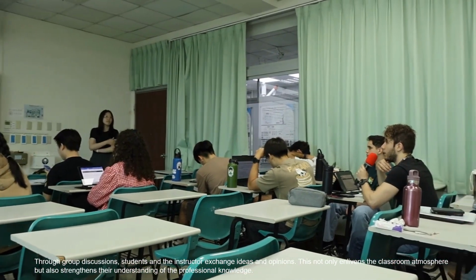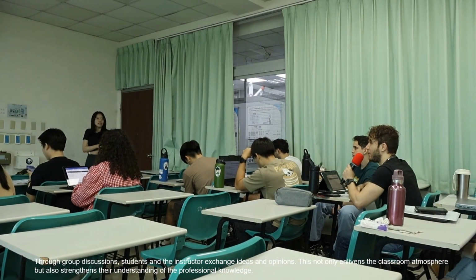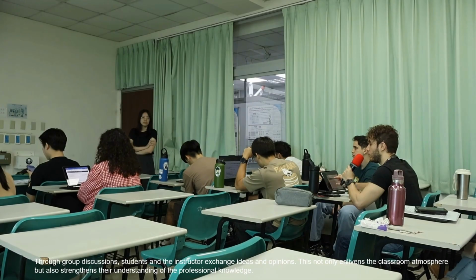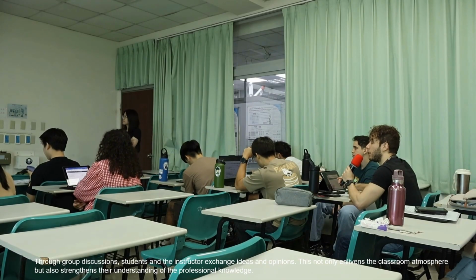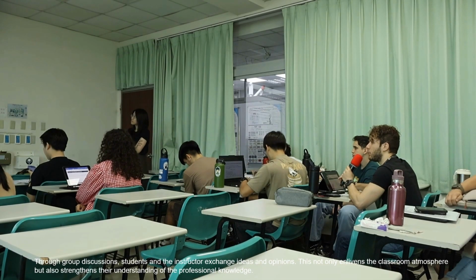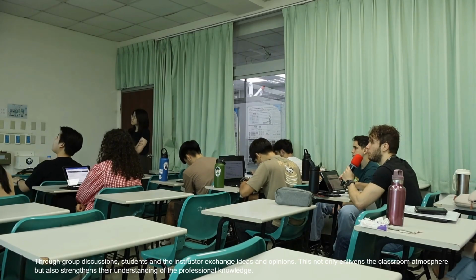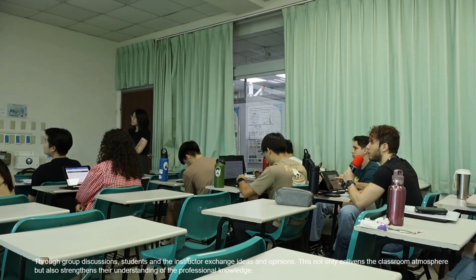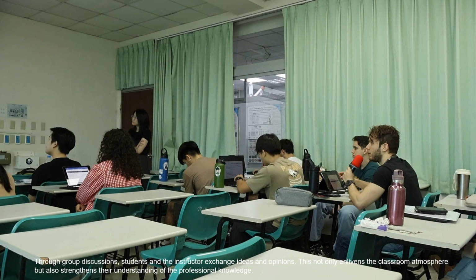We did a similar thing as the previous ones. In this case, we divided the ultimate load by 3, so we got 84. Then, using the curves, we obtained a settlement for the working load between 2 and 3 millimeters. We selected the lowest allowable settlement, which was just 6 millimeters. So we concluded that the pile will be governed by capacity.